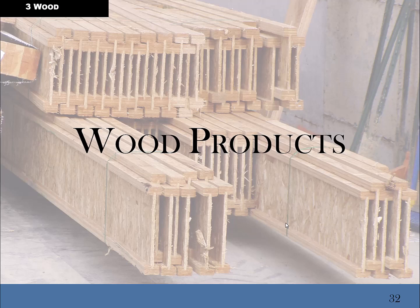Okay, so here we're looking at wood I-joists. This is engineered lumber. The trees don't grow like this. They're putting together and making a wood product that is a beam, an I-beam, in fact. These are typically used as replacements for 2x12s, for floor framing and sometimes roof framing. They're very light and nice and rigid. They burn like crazy, though. They burn faster than normal lumber, so that's their big kryptonite, their big weakness.